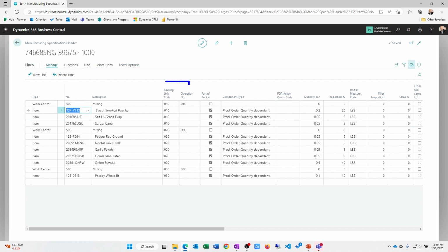So if you have the scenario where maybe my components are weighed, you go through a measurement step at step 1, so all of the materials need to be available, they need to be picked, they need to be at work center 1. I'm going to go through a measuring, a weighing step, and then I'm actually going to consume those in subsequent steps in the manufacturing process. These two fields allow us to separate demand from consumption, if you will.